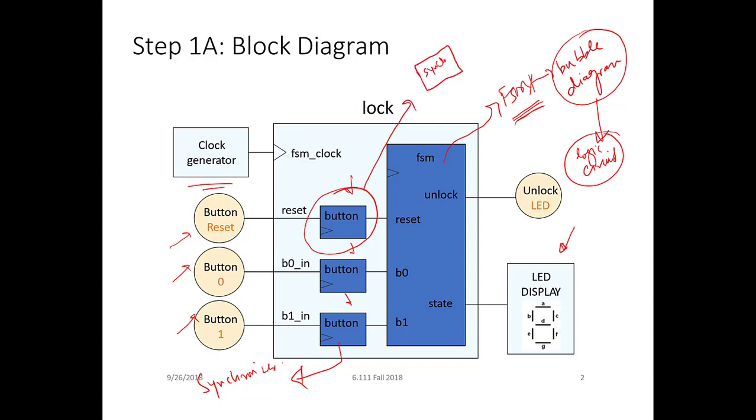One is a synchronizer and the other is a level to pulse converter. Now let me explain the need of these two. You already came to know that level to pulse converter is to convert the input from a user which can span multiple clock cycles, and the level to pulse converter converts it into exactly one clock cycle.